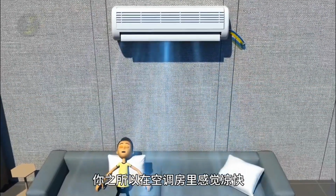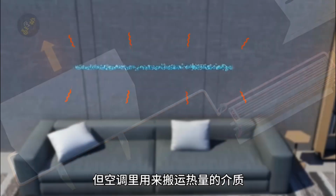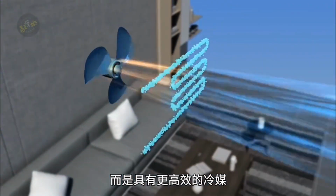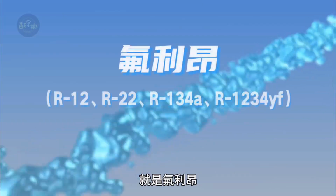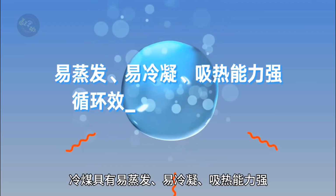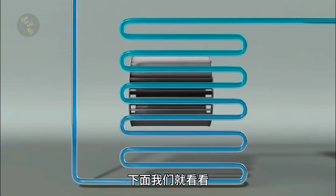The reason you feel cool in an air-conditioned room is that the heat in the room is moved out by the air conditioner, but the air conditioner uses something to move the heat. The medium for transferring heat is not water, but a more efficient refrigerant. Refrigerants are also called coolants, and the earliest and most famous type of refrigerant is Freon, which even became synonymous with refrigerants. Refrigerants have a series of thermodynamic advantages such as strong evaporation, condensation, and heat absorption capabilities, as well as being safe and stable.